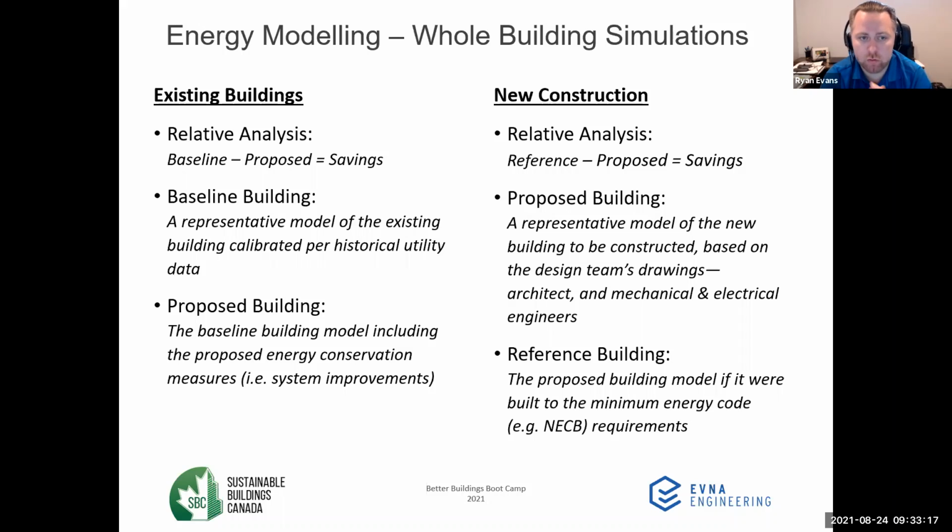So the way we go about doing a new construction analysis is that we will create the proposed building first, and that is the representative model of the new building that we're looking to build. And we're basing those model inputs on the design team's drawings. So that's the envelope enclosure details from the architect, and the mechanical and electrical details from the engineers.